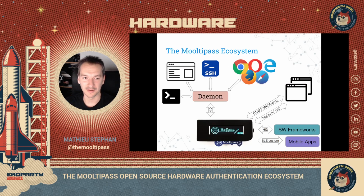Multipass ecosystem. Here, I'm going to go through each of its parts. So the device itself can communicate over USB or Bluetooth. On the USB and Bluetooth communication channels, we offer the HID protocol, which is a big word to say we are just sending 64 bytes every millisecond that we use to transfer data.